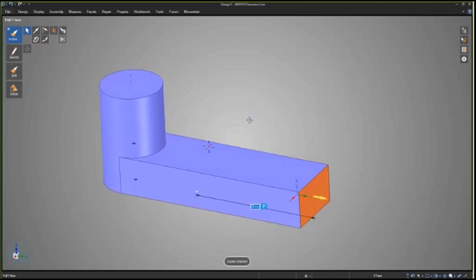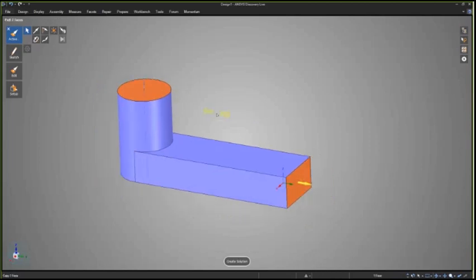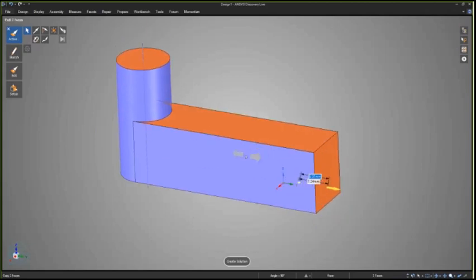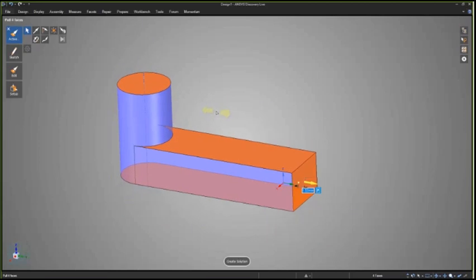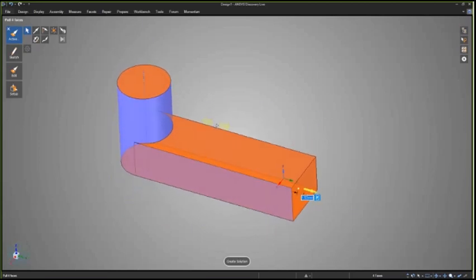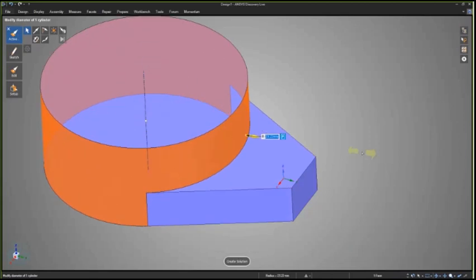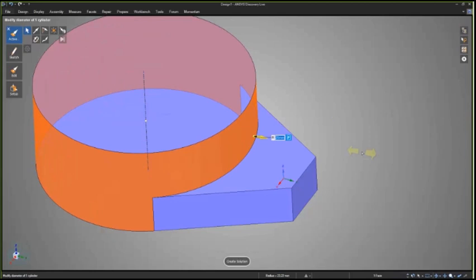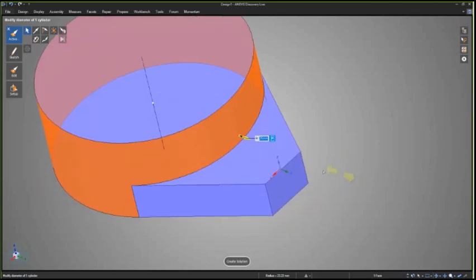But editing this one face isn't really that impressive. Where SpaceClaim and Discovery Live really shine is editing multiple things, taking both these faces and changing them together, 2 faces, 3, 4, it doesn't matter. It updates based on the geometry that's there. The same is true for the cylinder. If I pull that bigger, I can change the size, type in an exact value if I want, because I didn't know I needed it 25 at first, but that looks like the right size.